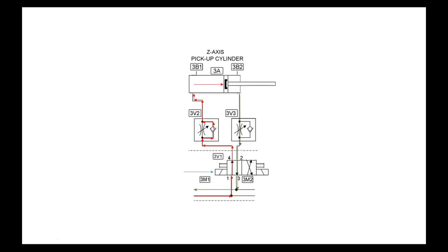Hydraulics doesn't make any difference, because hydraulic fluid is incompressible. So you can meter in or you can meter out, whichever one your plant decides to do. Pneumatics, we meter out. That's what that term means. Meter out means where you put the flow control valves.